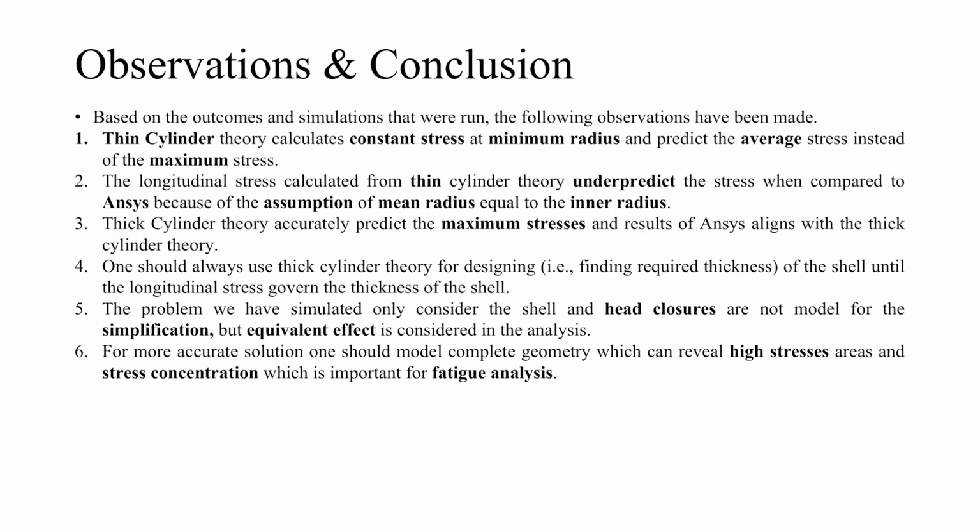Thick cylinder theory accurately predicts the maximum stress, and the results of Ansys align with the thick cylinder theory. One should always use thick cylinder theory for designing, finding the required thickness of the shell, until the longitudinal stress governs the thickness of the shell.